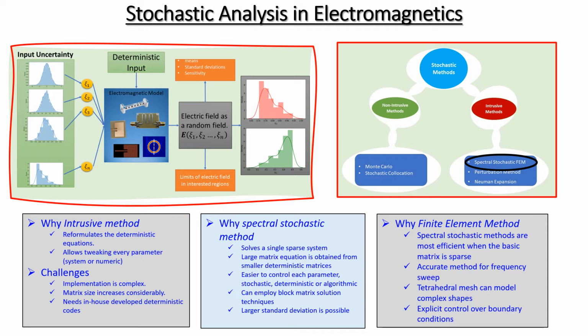Stochastic analysis is broadly classified into non-intrusive and intrusive. In non-intrusive, the deterministic solver is considered as a black box. The results from multiple runs of the deterministic solver are analyzed to get the stochastic response of the system. The examples are Monte Carlo and stochastic collocation. Intrusive methods reformulate the deterministic mathematical formulations to incorporate the stochasticity in the system.